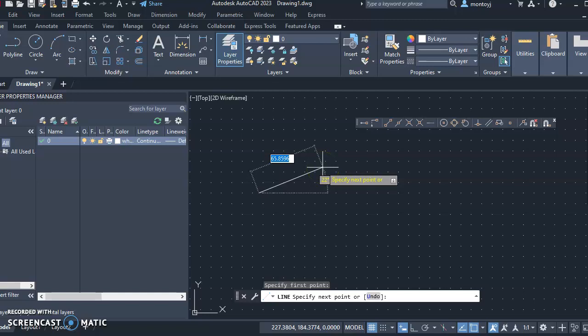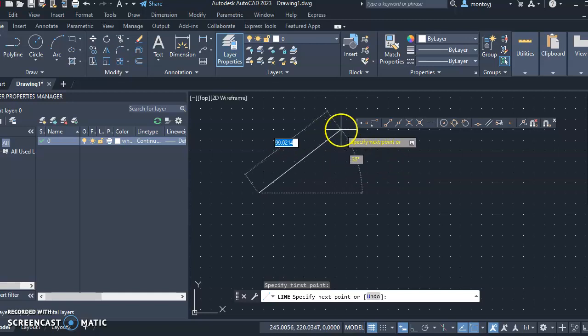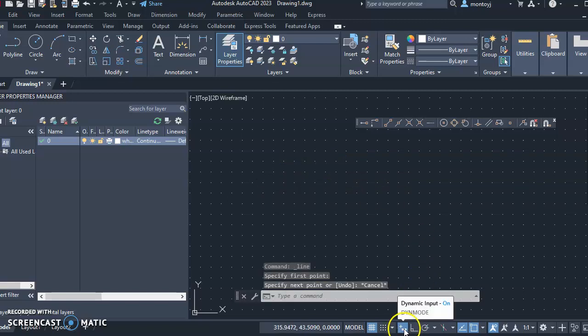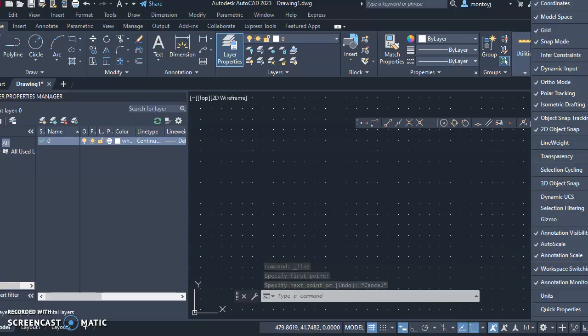At one point, I changed the type to yellow, and I'm kind of sorry I did that, because now it thinks I want yellow type in that little box all the time. So I'll change that while we're there. If you don't have this button, look over here at the 3 hamburger. It's not near lunch, so I'm not getting hungry when I say that. But we'll go to the hamburger settings, these 3 stacked lines, and we're going to look for dynamic UCS. Okay. There, we've selected it. It should show up. Let me verify this by turning it off.